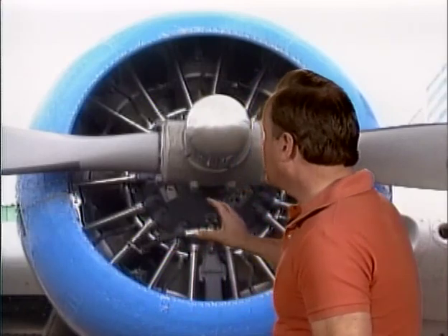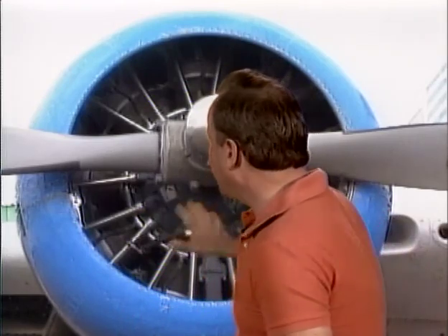Now, how do you know that you have the engine sufficiently pre-oiled? Well, oil will come back from the engine return or the oil pressure gauge indicator port. Now, the return line or the indicator port are the last places generally oil would get to. And if you've got oil to one of those two places, you have the engine sufficiently pre-oiled.